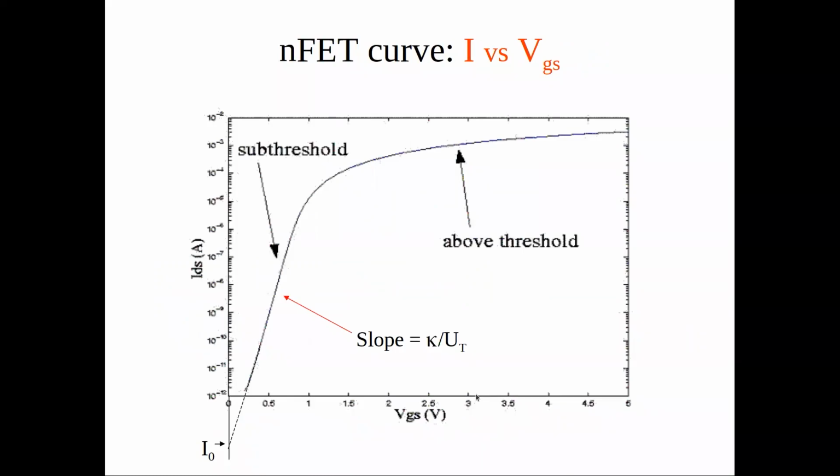I0 is the current that you would have if you had a 0 VG. So it's typically, depending on the process, but with this old chip, it was 10 to the minus 15, 10 to the minus 14 amps. So 10 femtoamps. VDS, in this case, we are assuming probably when we took this data, it was anything above 100 millivolts.